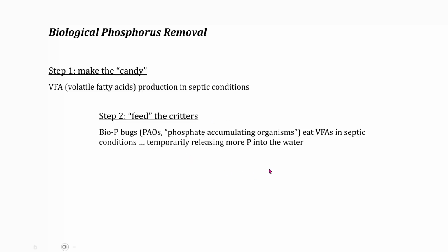And through a crazy little quirk of nature, this later becomes a great process control tool. They actually release phosphorus as soluble phosphorus, as orthophosphate, back into the water. So you can measure how effective these first two steps are by monitoring with the phosphorus, soluble phosphorus, the orthophosphate, going into these vessels and coming out. And if you get the right ratio of increase, actually increasing the amount of phosphorus, then it tells you have a great environment.